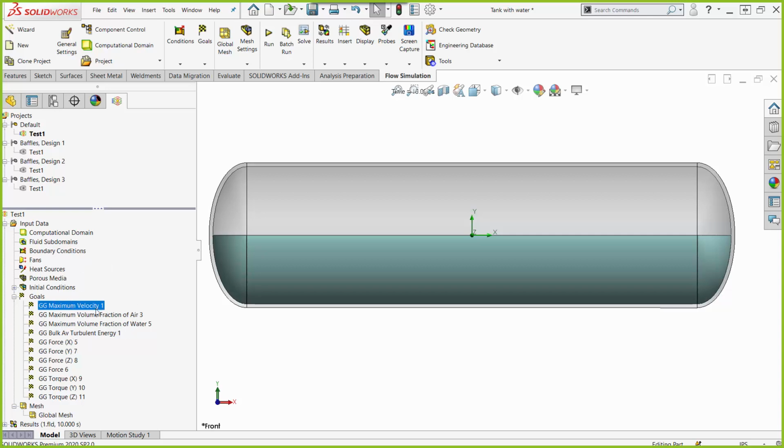So that's why I have this in here. And then I've got volume fraction of air and water. In this case, those are fixed volumes. I want to make sure those stay fixed, right? And that I didn't mix something up. In case you're brand new to Flow, these are global goals. That's what GG stands for. So it's measuring that over the entire 3D volume. Okay, so that was my goal setup.